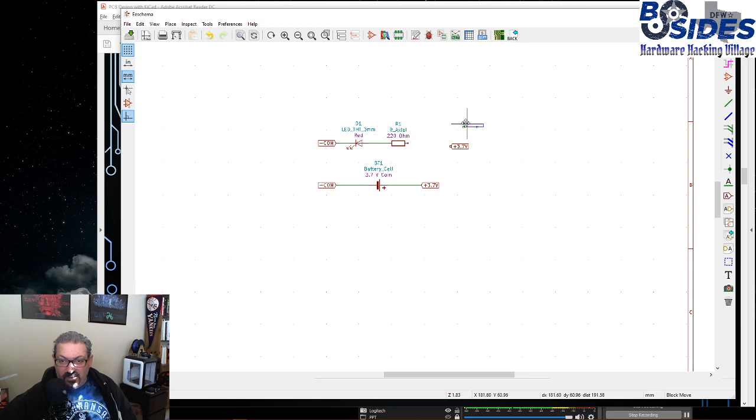And then as far as how you tag them together, instead of doing these global labels, I could have just connected them up by drawing lines between them. So let's say I didn't have this and I didn't have that. I could just take a line and connect these here. And this is a wire. So I use the wire tool and I connect those up. And I could do the same thing on the other side. And then just delete that to get rid of something. So I'm going to put it back the way it was.